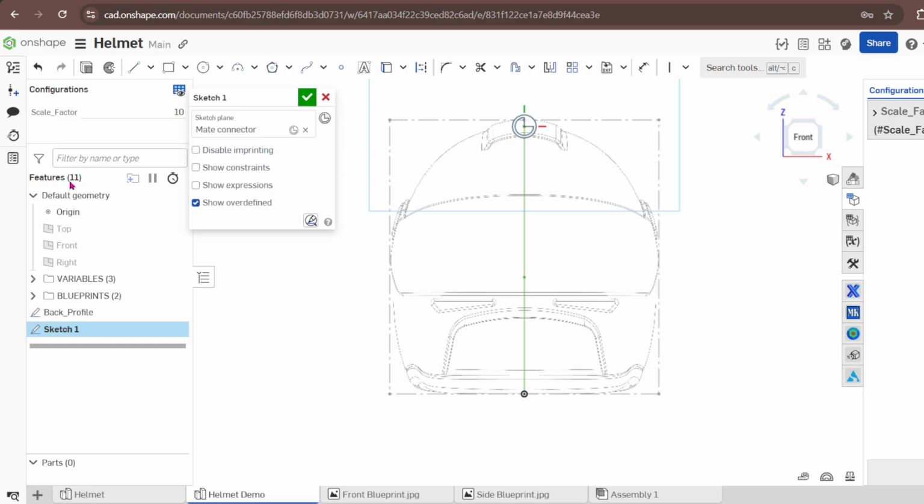You have to reduce. The more you reduce these ones here, the more someone is able to understand your design. Make your design easy to understand. Reduce a lot of features. Don't bury features. Sometimes you can sketch something, extrude, then extrude cut to remove it. Those are not good practices. Ensure that your design is following all the good practices for design.